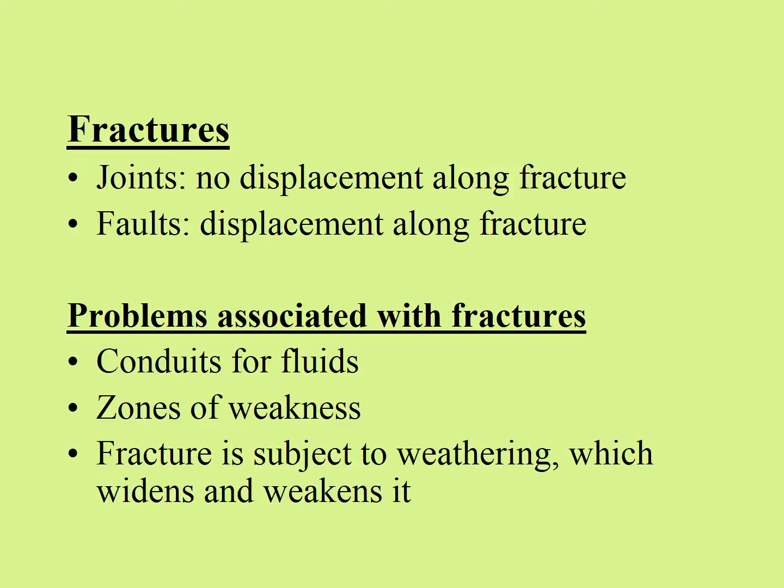Some of the problems associated with fractures are that the rock might have been very resistant to the passage of fluid, but with the introduction of fractures, they can constitute conduits for fluid passage. In addition, if you have high density of fractures, lots of fractures in a particular part of the rock, you could have zones of weaknesses at those locations where fractures are more abundant. And another problem with fractures is they are subject to weathering, which can widen and weaken the rock along the surface that they leave behind.